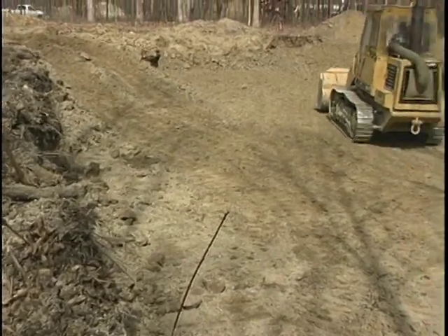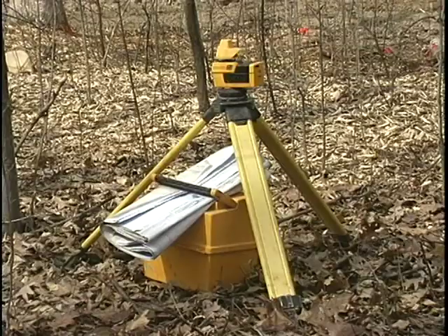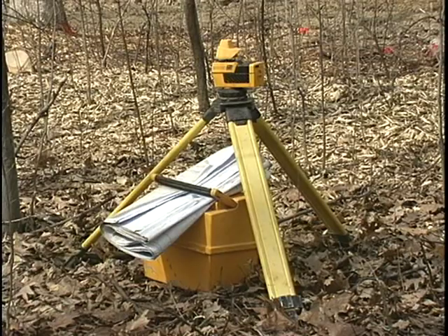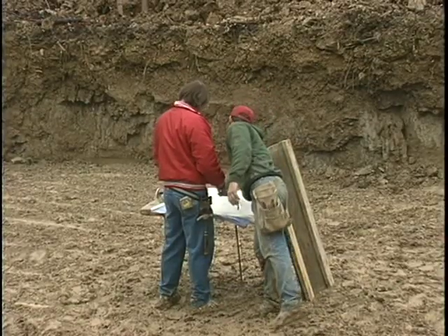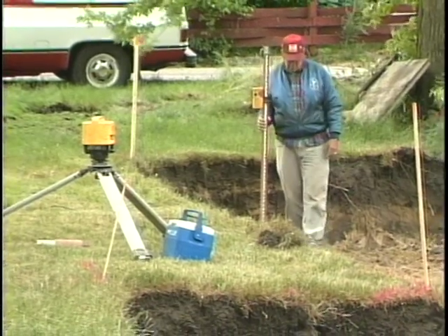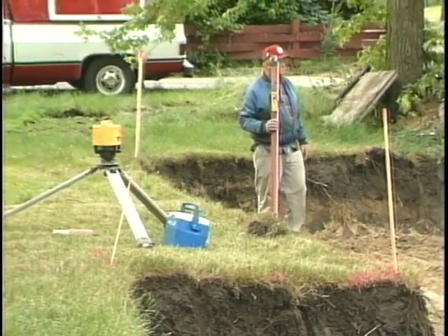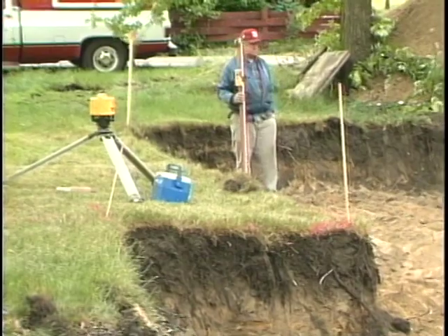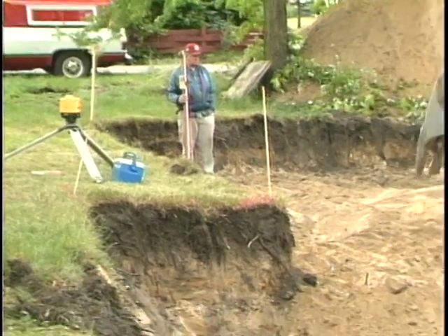The depth of the excavation can be calculated from a study of the vertical section views of the architectural plans. Today, a laser transit level and a laser detector mounted on a graduated level rod are used to quickly and accurately check depth of excavation.